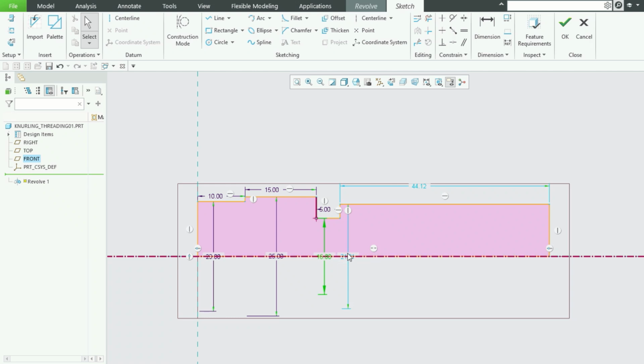And then this dia should be 3/4 of 1 inch. So 3/4 times 25.4, because we have taken the metric unit template. That's why we have to multiply 3/4 of 1 inch by 25.4 mm.